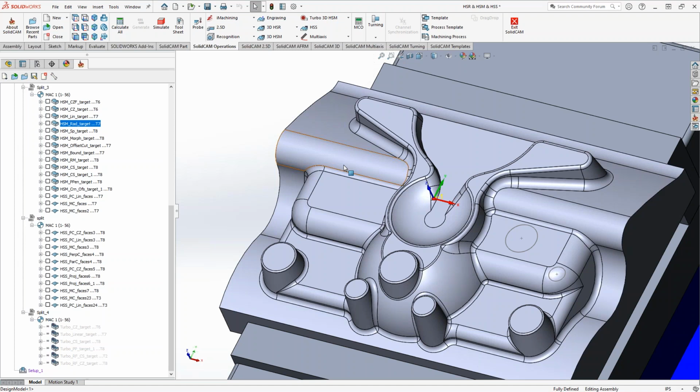Multi-axis constant stepover is a great toolpath, but I would use it sparingly. I wouldn't use it just as a hammer, like Kevin said, with the blanket. I wouldn't just blanket a toolpath on here and be done, only because that toolpath changes directions a lot, so it might be a waste of cycle time. At least that's what I would say.